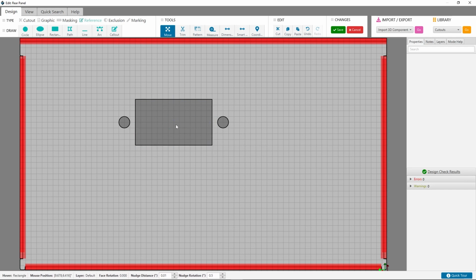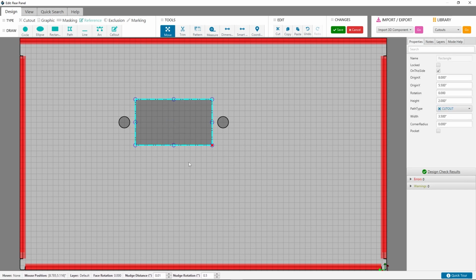After clearing your selections, hold down the Shift key, select the reference circle first and then the other cutouts. Right-click and then select Group. Now you'll notice that the origin is perfectly placed at the center of the group. The reference circle will always be displayed with the cutout, but it will never interfere with anything.